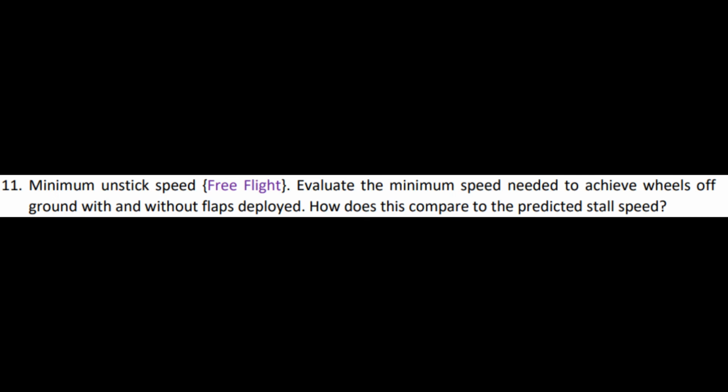It was found that the minimum unstick speed without flaps deployed was around 26 meters per second. With flaps deployed, the speed dropped to around 20 meters per second. As the velocity is supposed to be at around 10 meters per second, these values differ greatly.